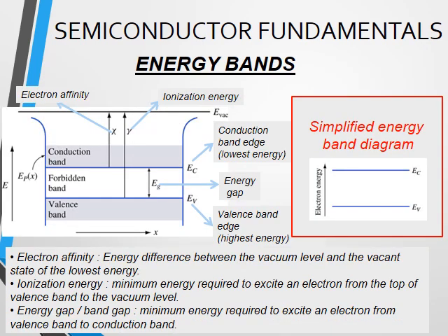We then simplify the band diagram without having to draw the atoms near the valence band. The things that are important in the band diagram are the conduction band edge, showing the minimum energy value for the conduction band EC, the valence band edge, showing the maximum value of valence band energy EV, the y-axis showing the energy and the x-axis showing the location.